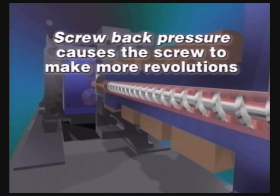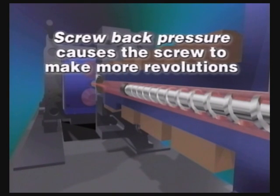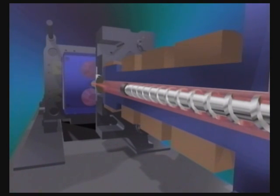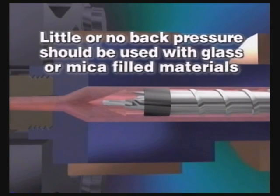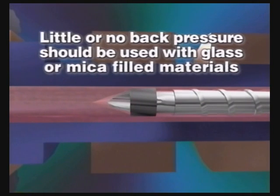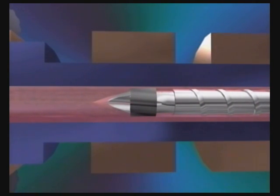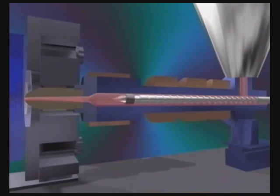Screw back pressure causes the screw to make more revolutions. These additional revolutions create more shear heat, which can cause material degradation. Little or no back pressure should be used with glass or mica-filled materials. Back pressure breaks up the filler, which reduces molded part quality. Increased back pressure also accelerates wear on the screw and barrel.